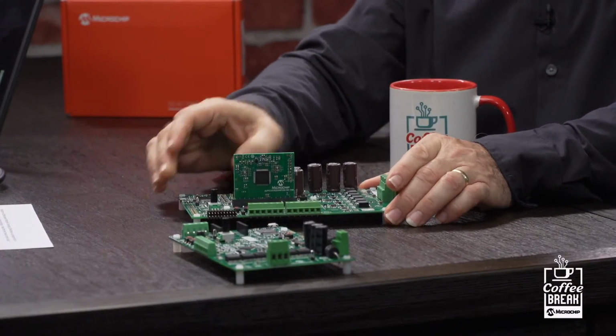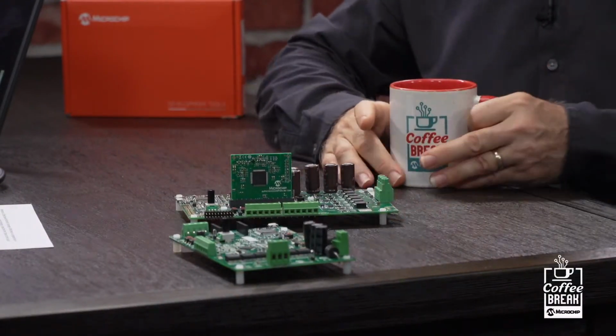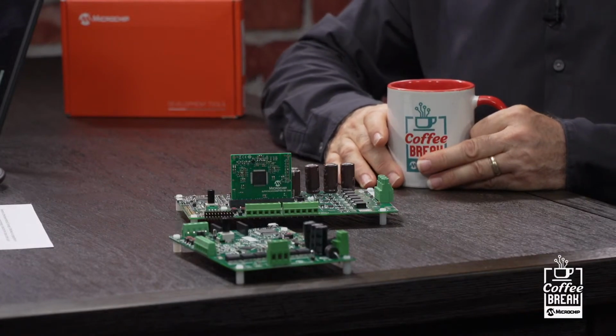Awesome. Another question is, besides the MCLV 48 volt 300 watt inverter board, are there other boards that use the new motor control DIMMs? Yeah, we obviously want to get a lot of reuse of our DIMM design concept, and so we have a whole series of boards planned that will use these plug-in DIMMs. The next one, which is almost completed design, is a high voltage board, MCHV 230 volts, 1.5 kilowatt design. And after that, we plan a stepper motor control board, and then a multi-motor board that will also use the DIMM concept.